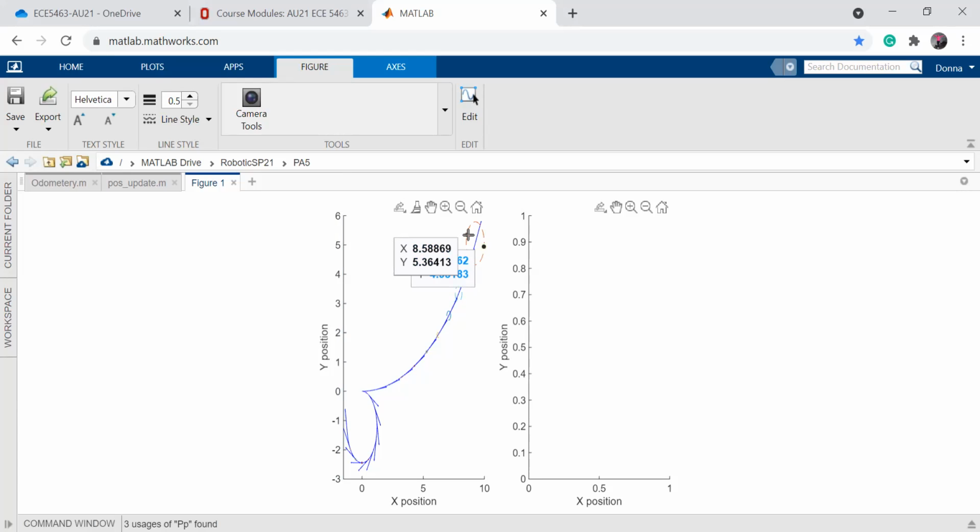Usually for a car, like the mobile robot, you use the full PID controller, all 3 terms. The main reason is you have error accumulation, so you have to have the integral term. For the manipulator that we used, you can get by with PD. But for these, because we have error, we have to use all 3 of them. Usually you see PID, but the values might be small.